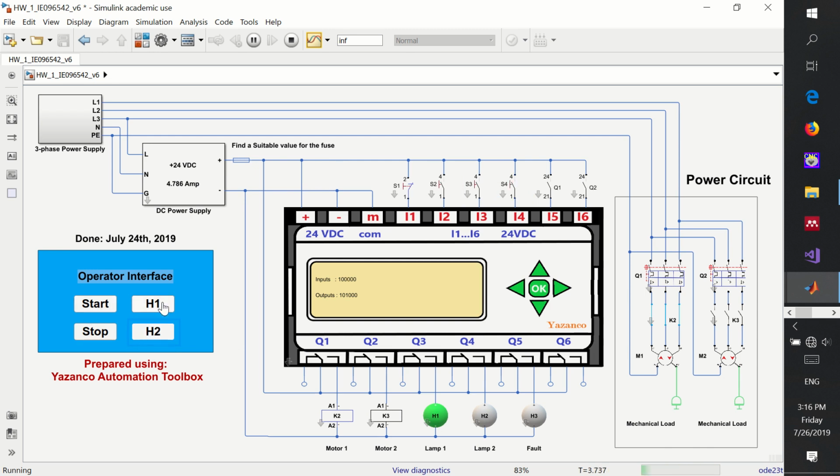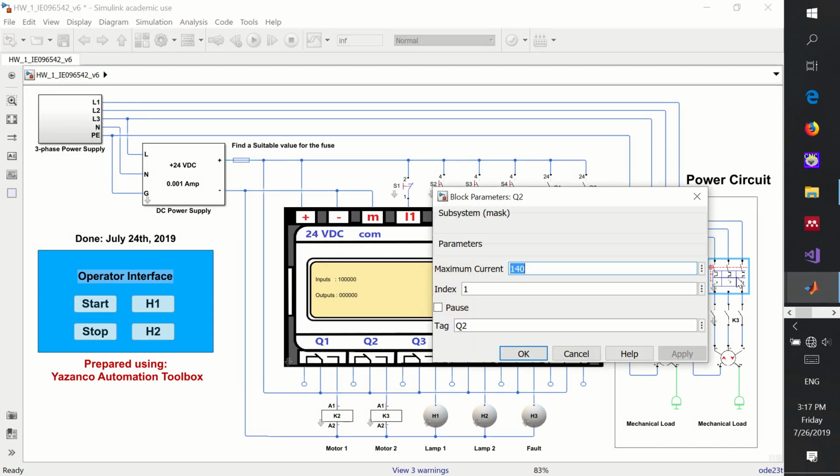So again, if we need to stop it, we need to press the stop push button. Okay, and we need to start the system another time before being able to start the second motor, as you can see here. Now, pressing H1 will actually cause nothing. Okay, so we need now to stop it. Now, to test the default behavior, let's assign maybe a different value for the overload.